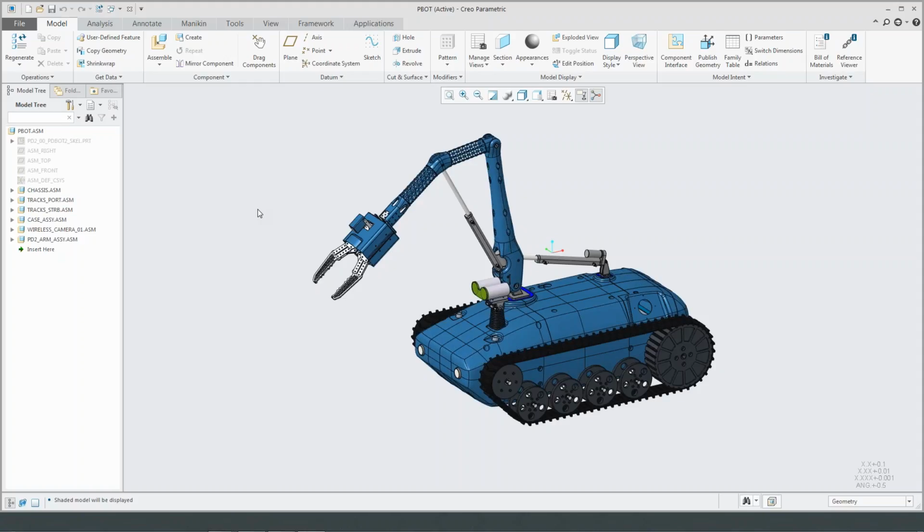Creo Parametric is a parametric modeling tool, which means that it relies on relationships. You build dimensions, and it creates parent-child relationships. So if I create a box and then I create a hole within that box, I have to reference an edge for that dimension to drive off of. And it's very good for manufacturing because as things change, they update accordingly because of the design intent you build into it.